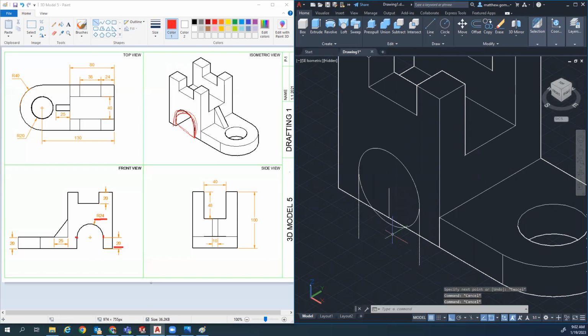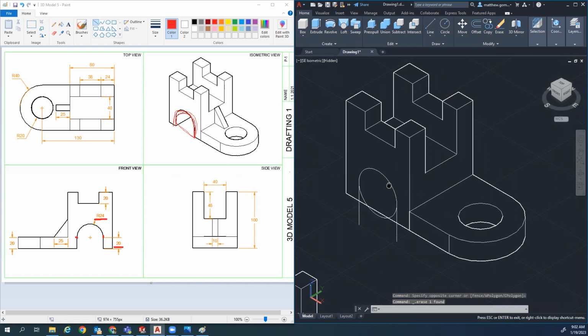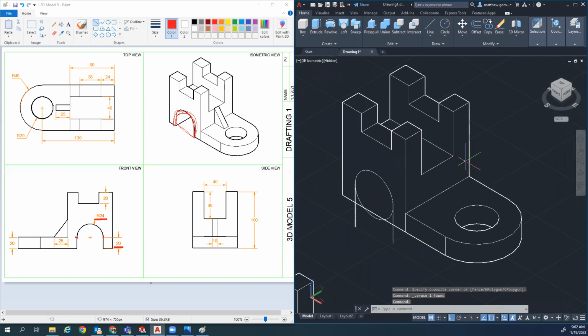Now, when you're trying to trim in 3D, like I'm using the trim tool right now, this won't trim. So ideally I would trim this, but it doesn't trim. So what you're going to have to do on this one is press pull this 3 times because technically there's 3 different faces that you have to press pull. I'll show you what I mean.